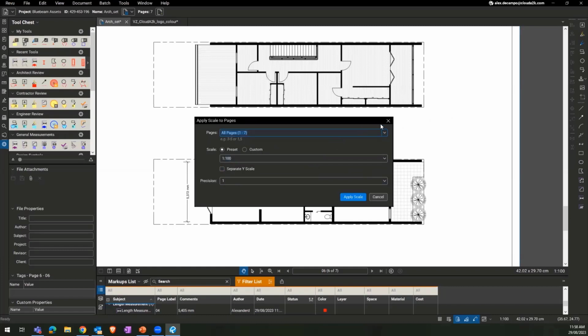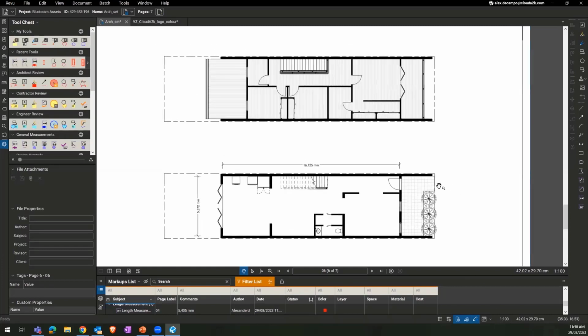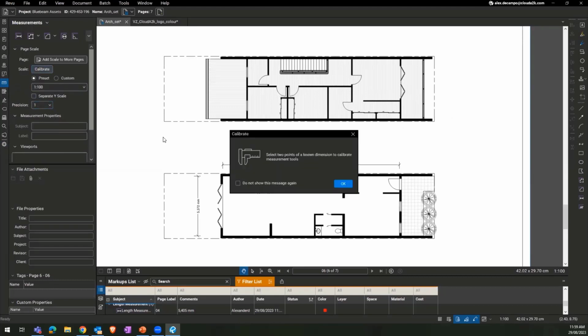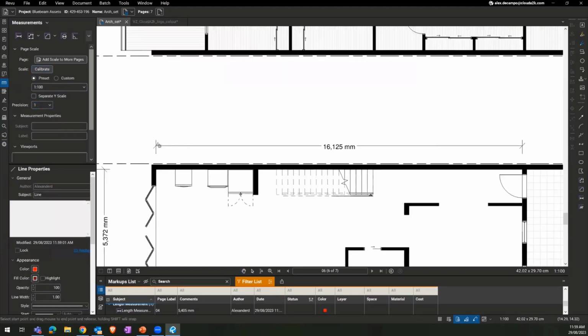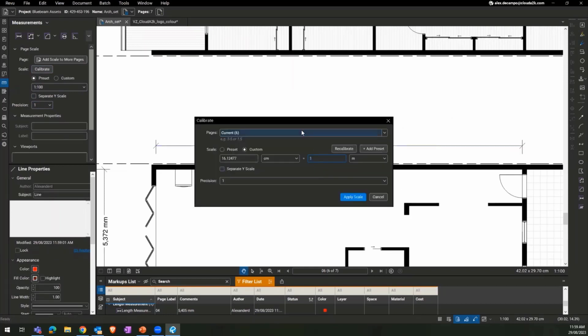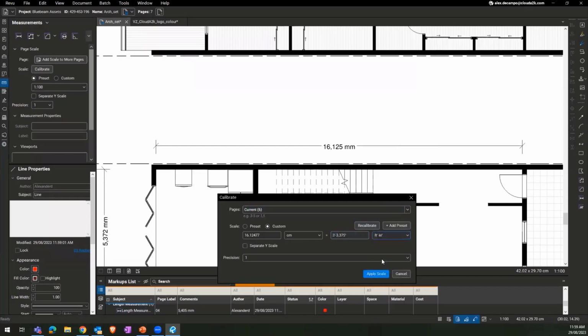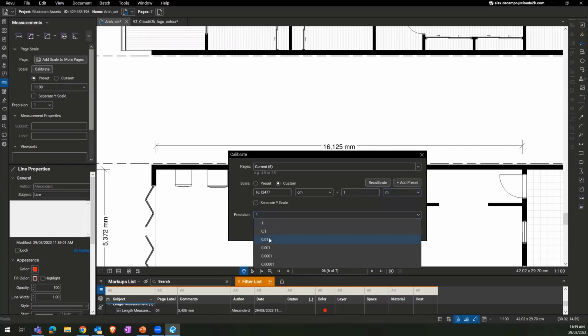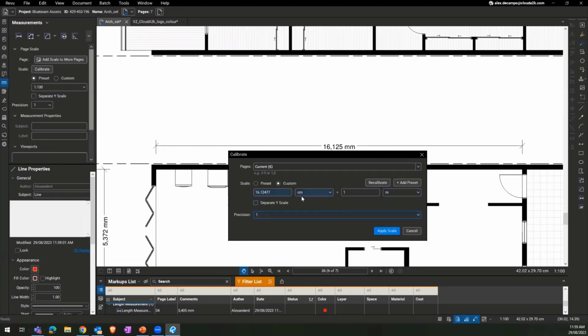As for the scale precision as a default, yes and no in a way. If I open up my measurements tab here, precision as 1 on this tab will sort of apply. If I click calibrate and use this measurement for calibration, and change it to millimeters, feet, inches, whatever, the precision will stay as 1. So if you've changed the precision, it'll stay that way. If I then go back to meters, the precision is still 1 when it should be 0.01. It's just one of those things you have to look out for every time you calibrate. Just change the precision while you're there.